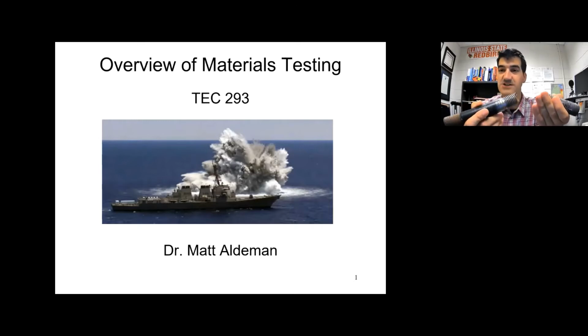But this is even larger than the specimens we're going to do tensile testing on. But that's basically what we did. This is basically a tensile test where we were torquing down the nut, which put this in tension, and whether it was due to substandard quality of steel or an inclusion here in the steel, we don't exactly know, but it broke. And like I said, it's not that unusual.